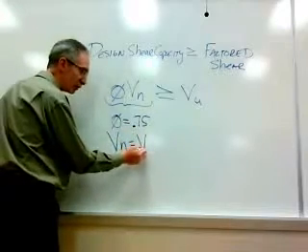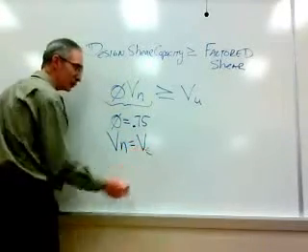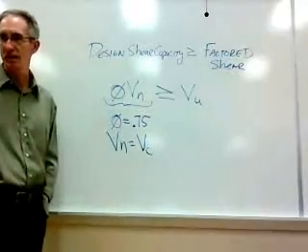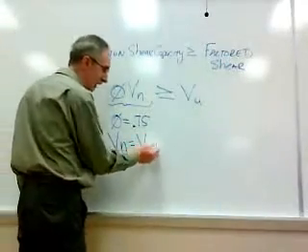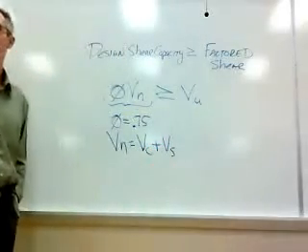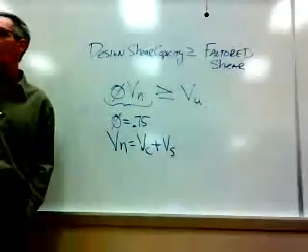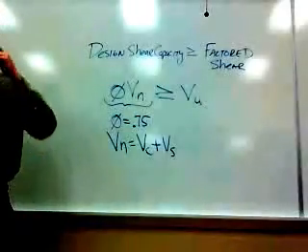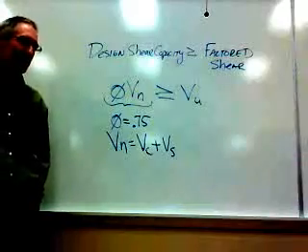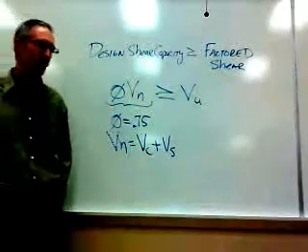Those two components, one we're going to call V sub C, shear capacity of the concrete. The other one we're going to call V sub S, shear capacity that the stirrups give us. Okay? So on the surface at least, it's pretty straightforward.